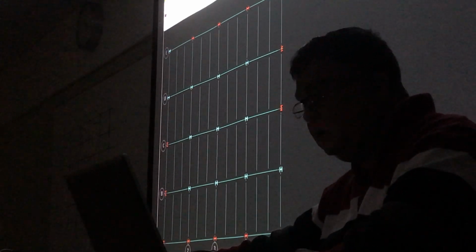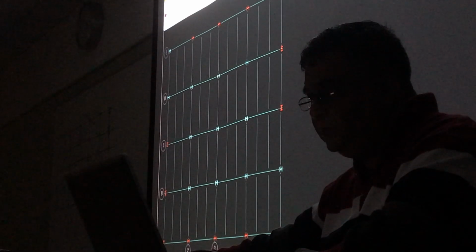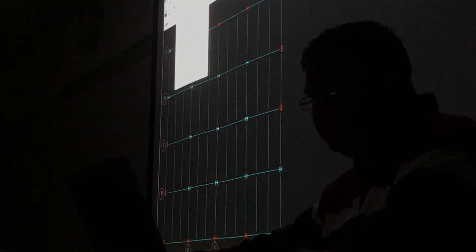I need the beams to be done. So I'm going to go Layout, Beams, Change Properties, and the framing should be lateral, and composite flat. Do I need composite flat? No, we expect that it will have negative moment, so don't worry about composite flat. Okay, it will be non-composite. Even if it is shown as composite, it will be non-composite. You don't have to worry.